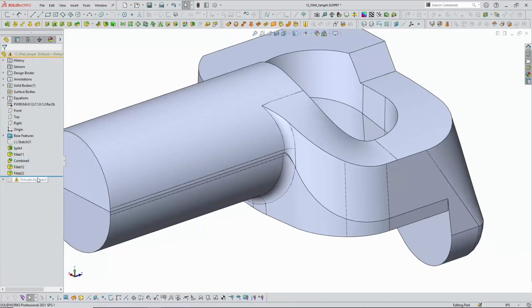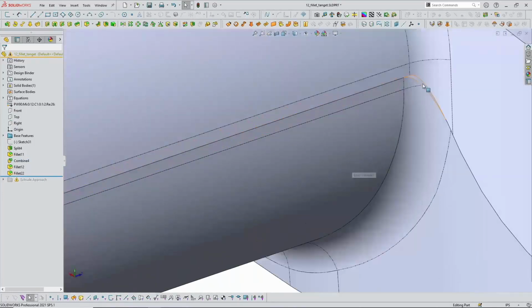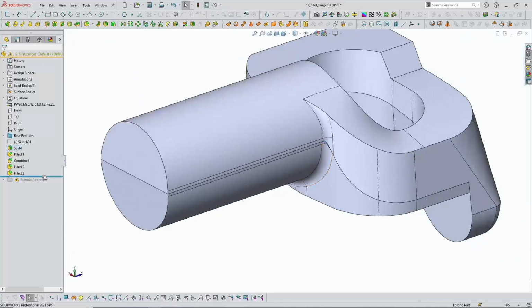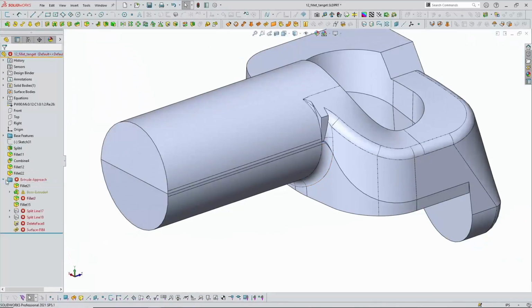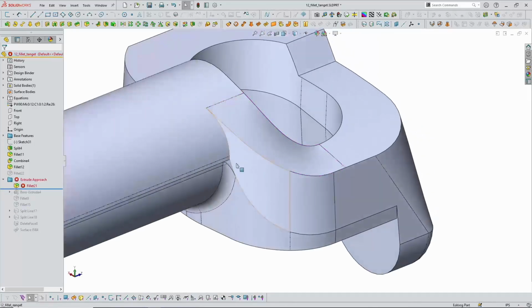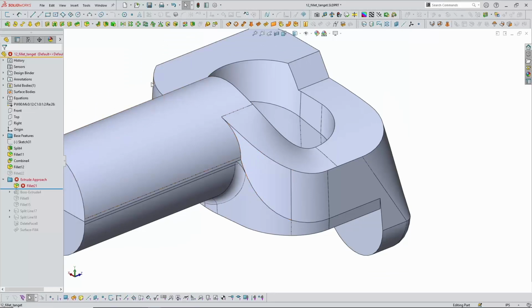But what if I wanted to have a perfect parting line? I wanted to get rid of this sliver face. How might I go about that? And the alternative way of adding new faces to the model, and this should work once this gets suppressed, perfect. The alternative way of adding these to the model is extruding material into the model to add new faces. This works in the same way as split, but it might be a little bit more convenient depending on what exactly you were looking to do.